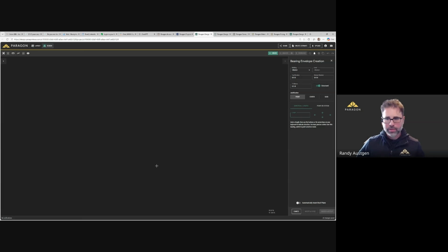So when I was first presented with the layout, the user interface, I saw all of these fields over here to the right, and I was moving my mouse a lot to get into this. And what I learned is you can use your keyboard for the direction and length. And while this may seem like a silly thing, it saves me a ton of button clicks and a ton of mouse movements.